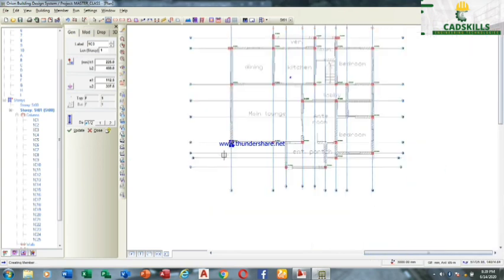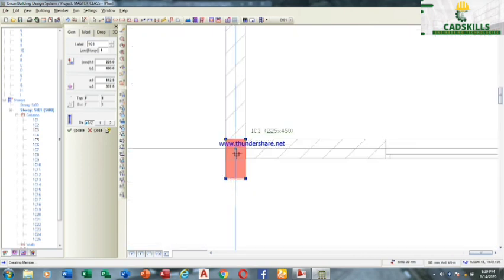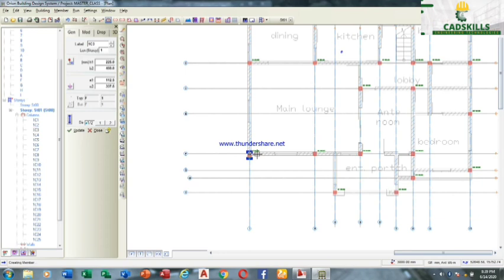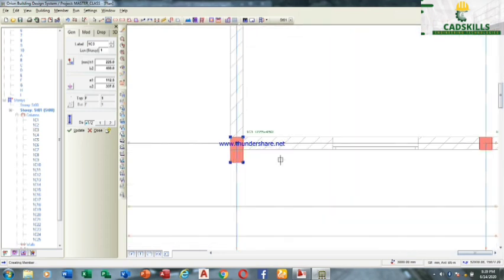Now what? Okay, there is another one I will show you, but I need to put the beam so that you can understand. When you have a 150 beam and 225, now you have the 150 beam here, you have 225 here. When you put your column here, it's going to be more than the beam by 75, because this is 225 to 150. 225 minus 150, the remaining one projects outside here.